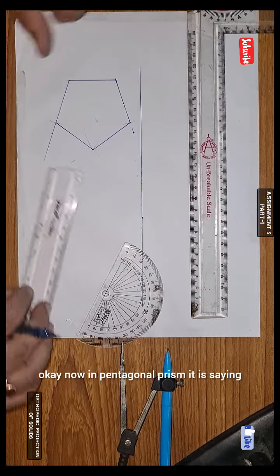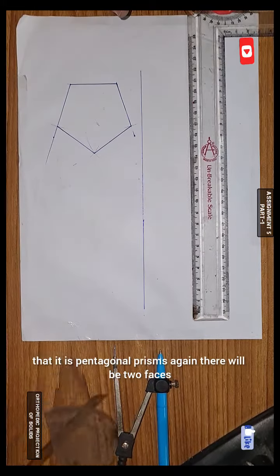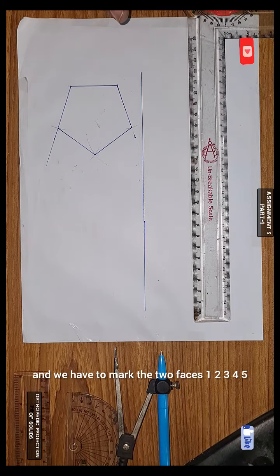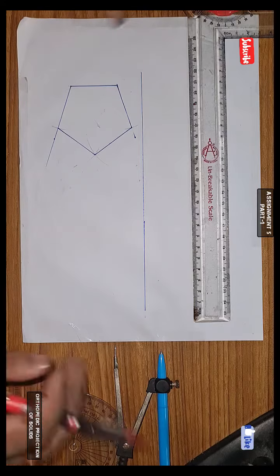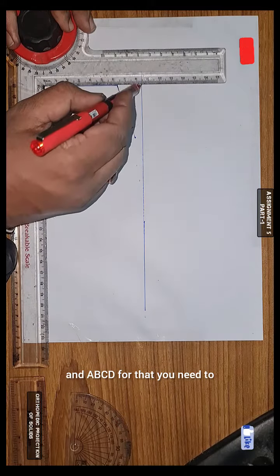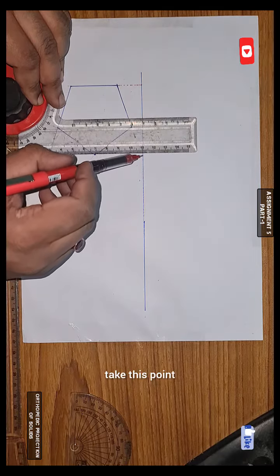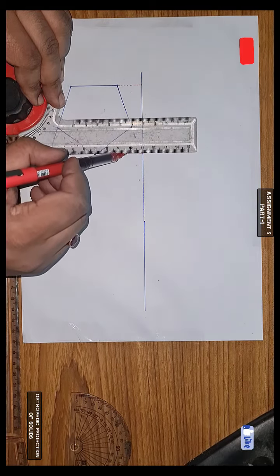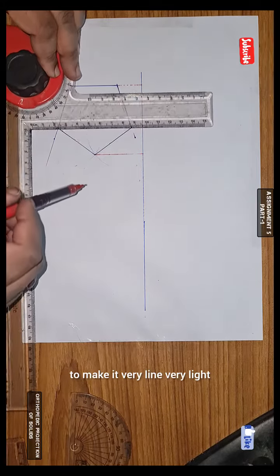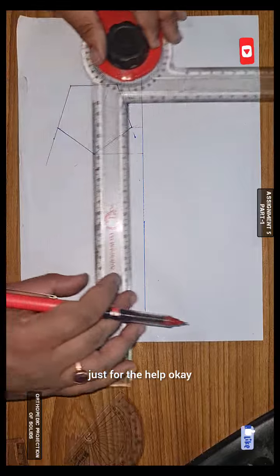Okay, now it is saying that it is a pentagonal prism. Again there will be two faces, and we have to mark the two faces 1 2 3 4 5 and A B C D. For that you need to take this point. This is just for helping lines, so you need to make it very light, just for the help.